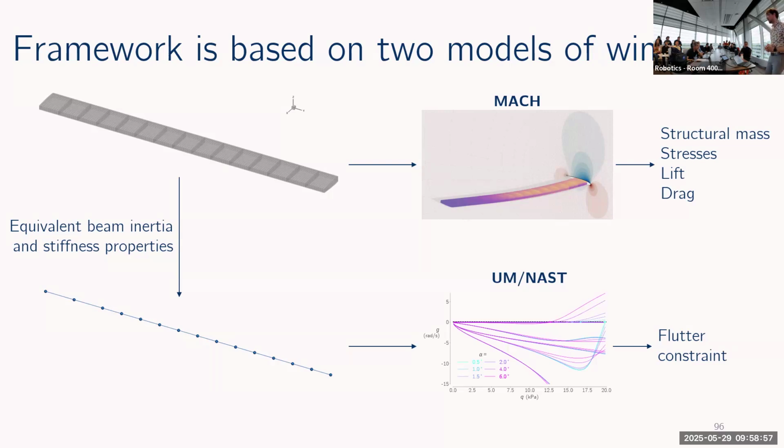traditionally maybe you would have thought higher aspect ratio wing, higher deflections, you might need to consider these things, but evidently not for static aeroelasticity. It doesn't seem to matter that much, but for dynamic things like flutter, it definitely matters, even at much more moderate deflection levels, like we see already in aircraft like the 787 in flight.